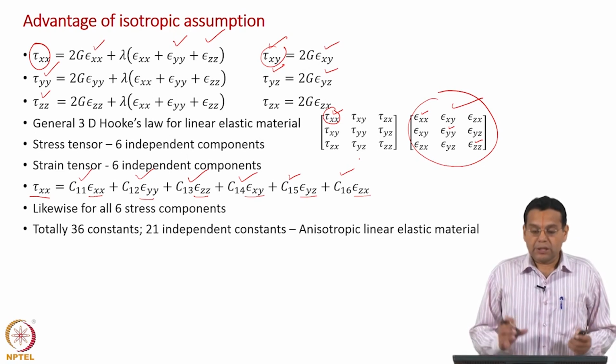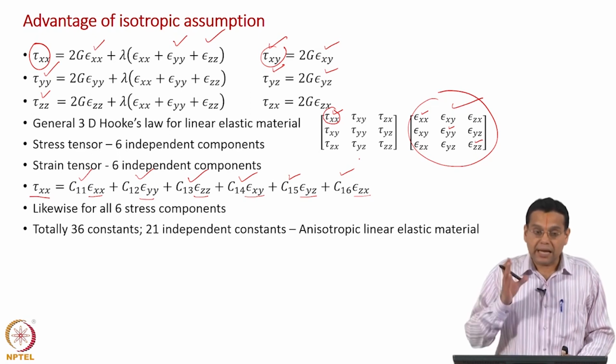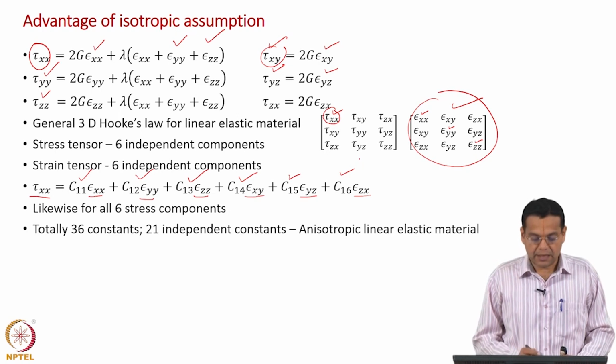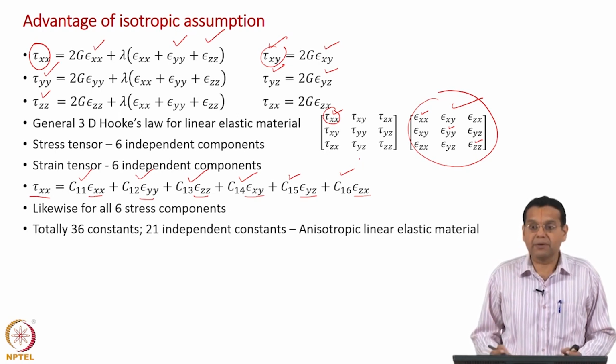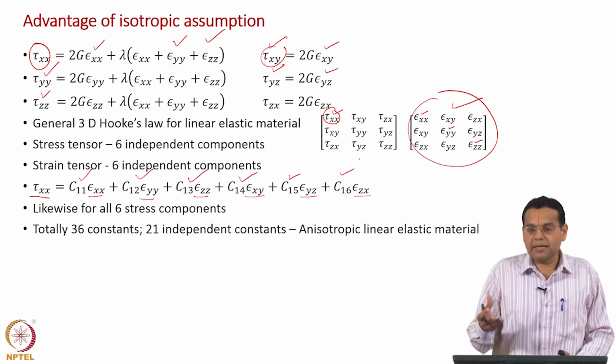So, if we are going to derive a stress strain relationship for a homogeneous anisotropic linear elastic material, we would end up with 21 material properties, because in all our relationships we need to write the properties depending on direction.